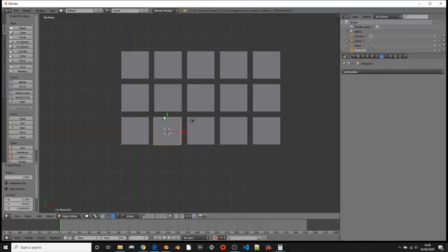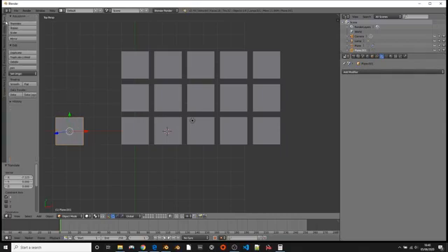So you see whenever I make anything you get these handles. I'm just going to grab that. So I could have come in and made a plane, and then copy and paste, or in the tools menu you've got duplicate, and then you'd use your translate to move it around. But this array tool is much quicker and much easier and gives us a nice uniform size.